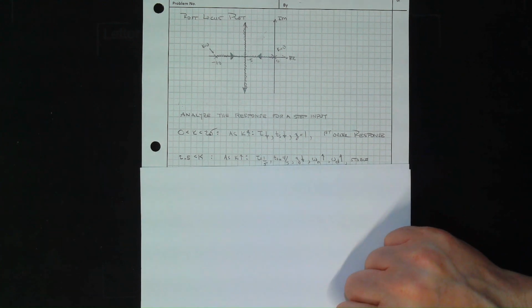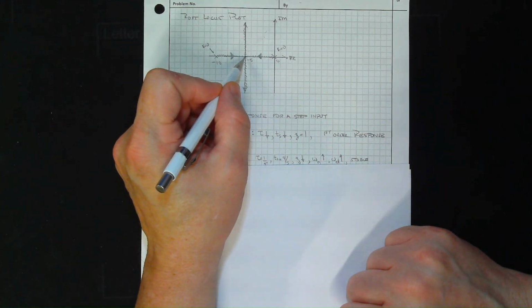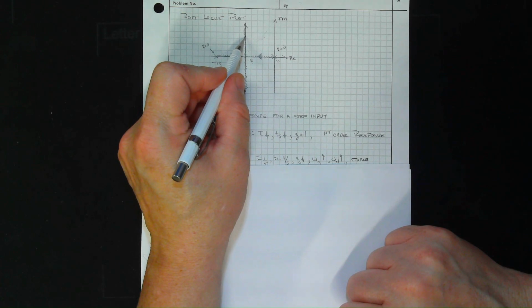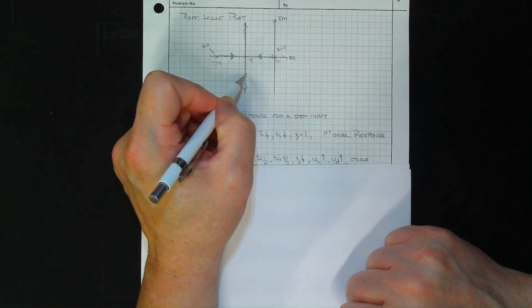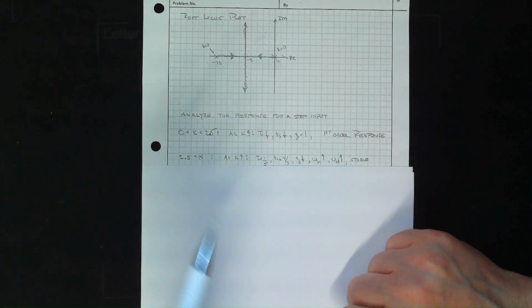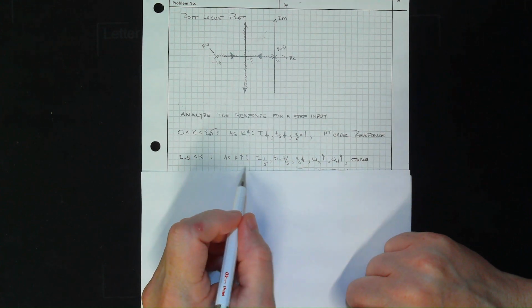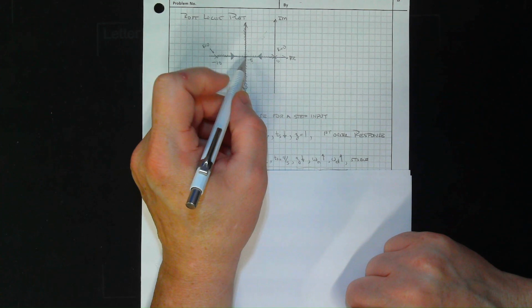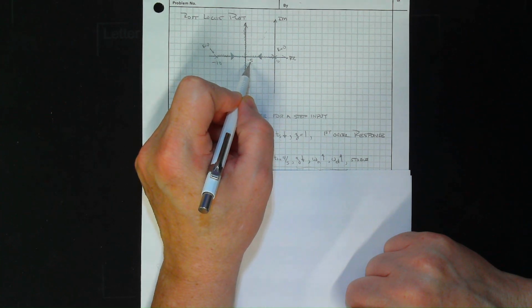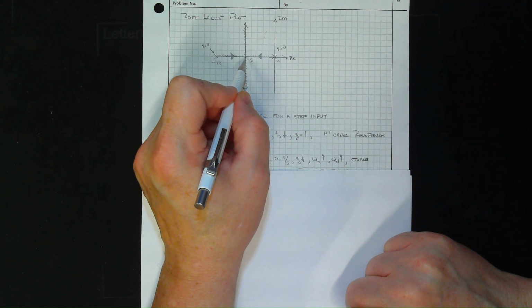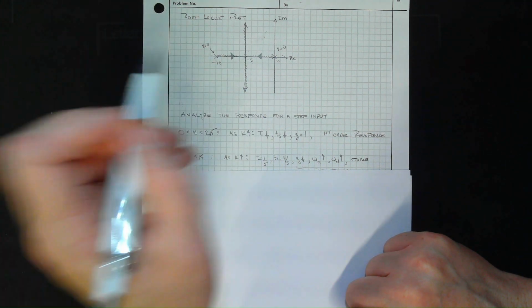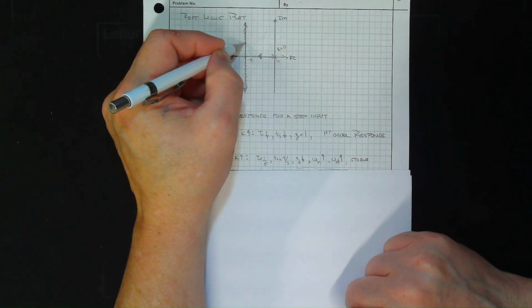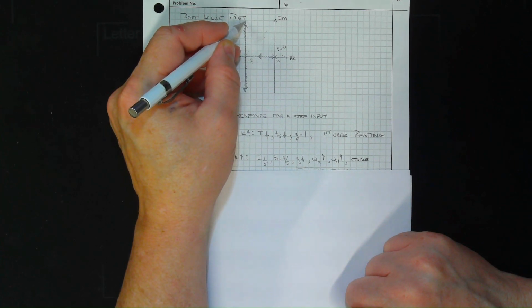All right. We'll let k be greater than 2.5. Now look what happens. One pole will be up here, and then you'll have the conjugate down here. So as k gets bigger, here we are, the real part stays at -5. That means the time constant is 1/5. The settling time is 4/5. They never change.